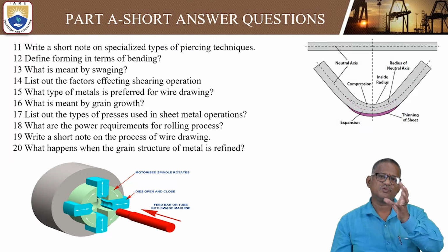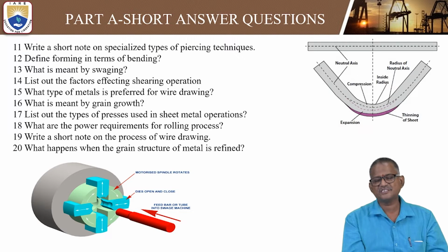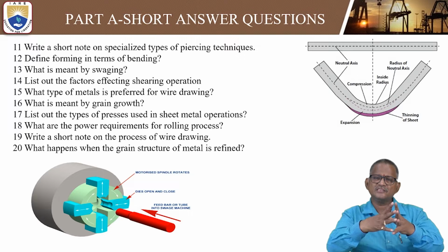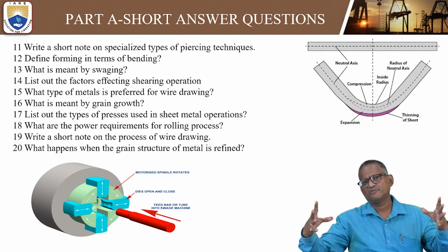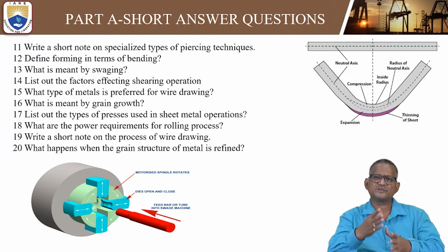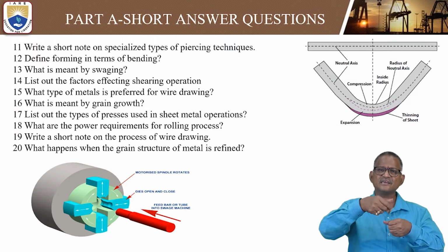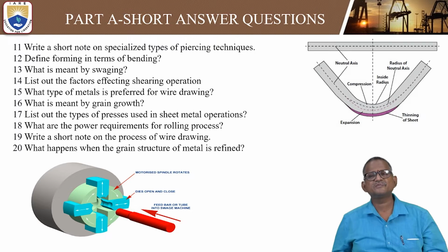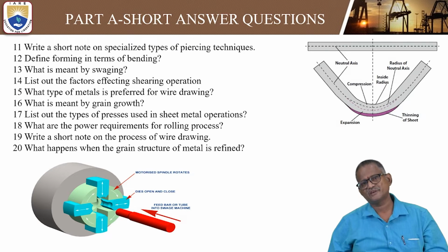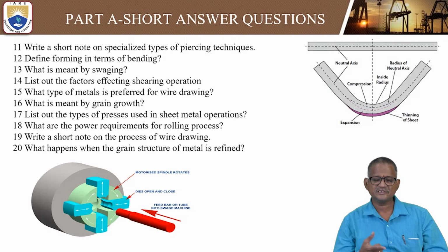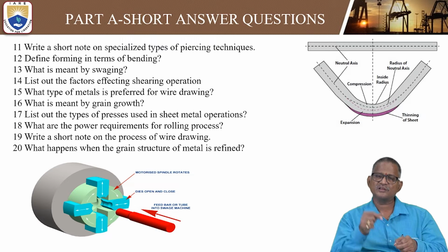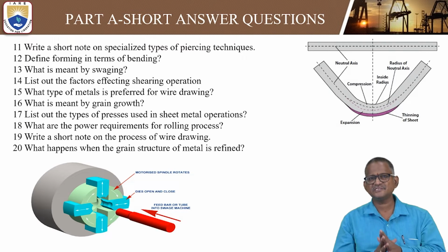Okay, so swage block. At a time, the 4-jaw chuck. You have studied in the lathe machine the 3-jaw chuck and 4-jaw chuck. In a 3-jaw chuck, when you open one jaw, all three open simultaneously, and when you close it, all three jaws close. But in this case, each jaw can be opened separately. This type of thing is especially applicable in some eccentric applications, with different diameters, where one cylinder and another small diameter cylinder can also be made.